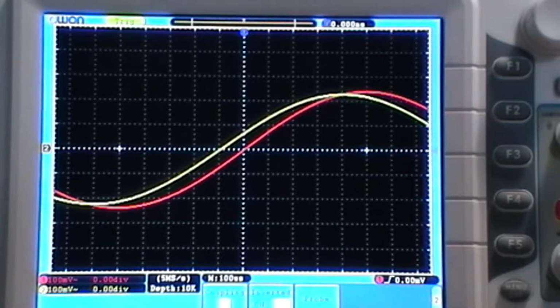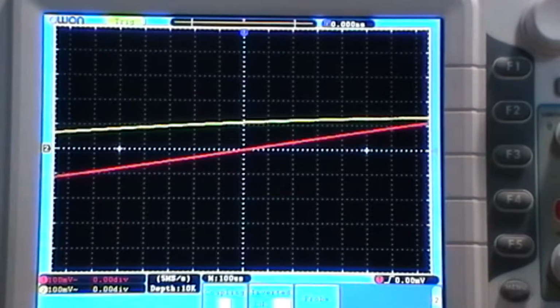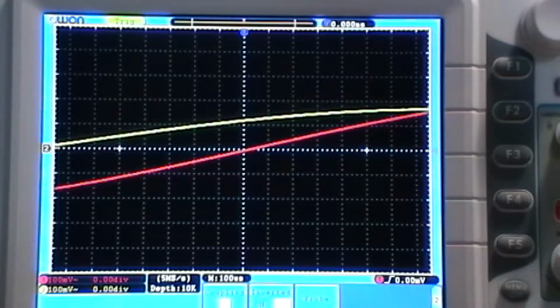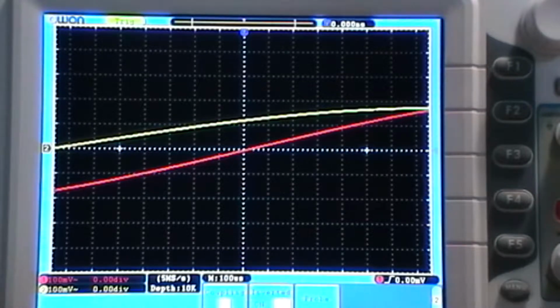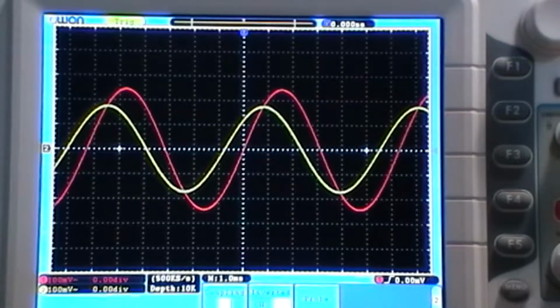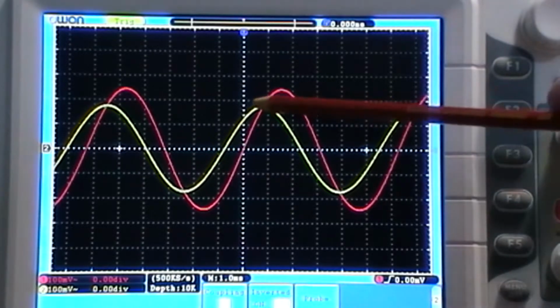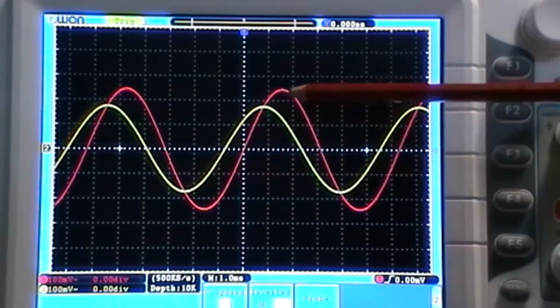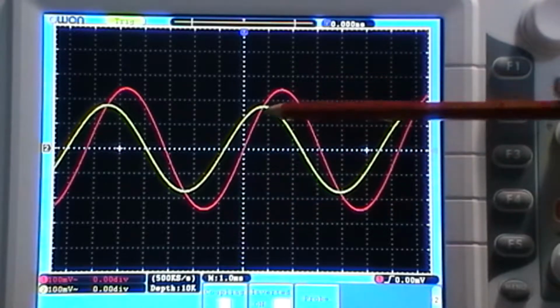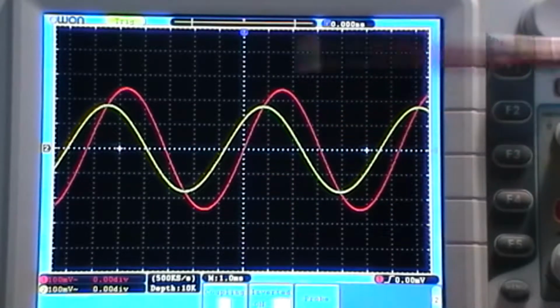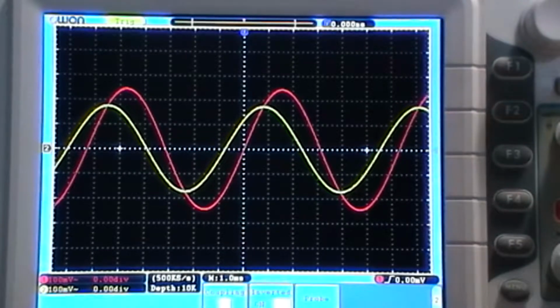So let's change that to 159 Hertz. There we go. And as you can see, I'm getting quite a lot of the signal through, but not all of it. Again, we've got this loss from the original signal. I'm getting about -3 dB, should be. I haven't calculated it, I'm not looking at that today anyway.